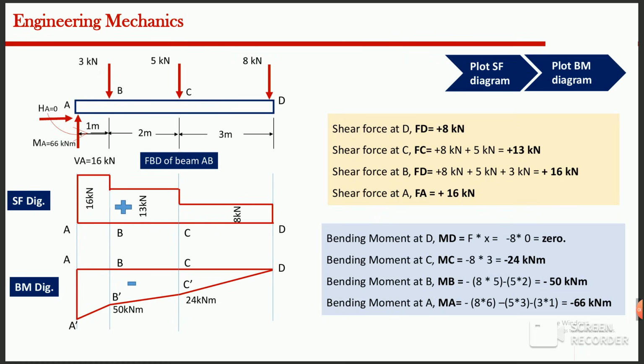Finally, using all the calculated values, we have to draw the diagrams. The shear force diagram consists of horizontal steps because only point loads act on the beam. The shear force changes suddenly at each load position.